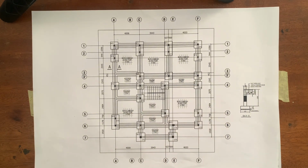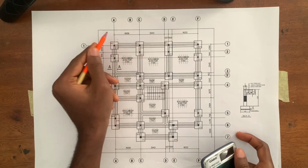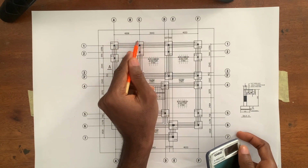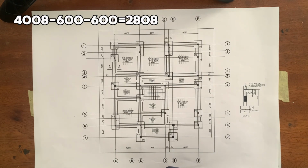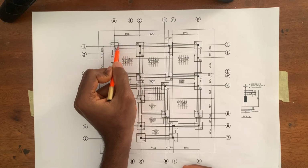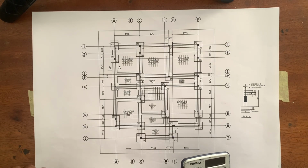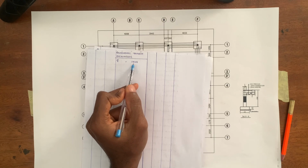So if we do the maths, we know that the center to center dimension from here to here is 4008. We can now minus half of the length of base type 2 and half of the length of base type 3. It will give us our trench. So let's do that: 4008 minus 600 minus 600 is going to give us 2808. So the dimension from here to here is 2808. All we're going to be doing now is to record it. So we've recorded the distance that we calculated, 2808.